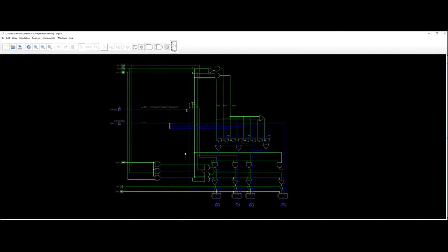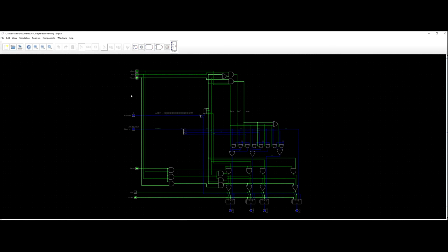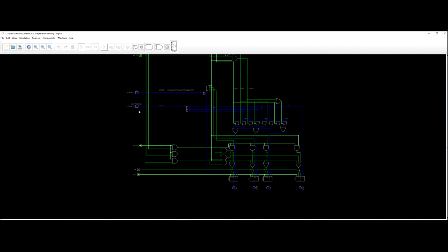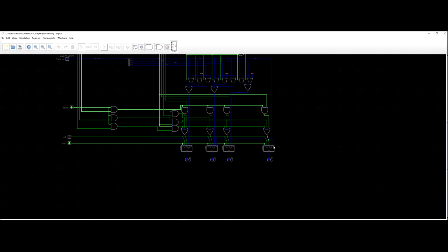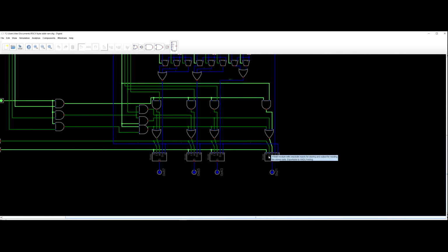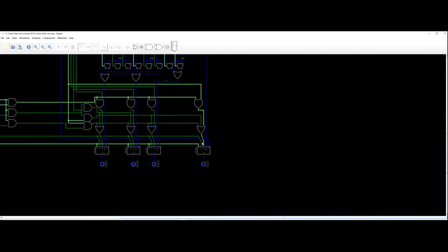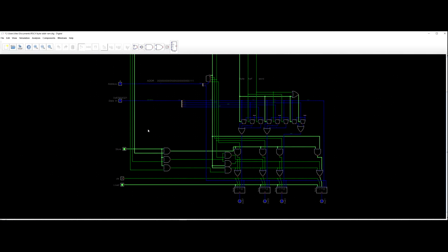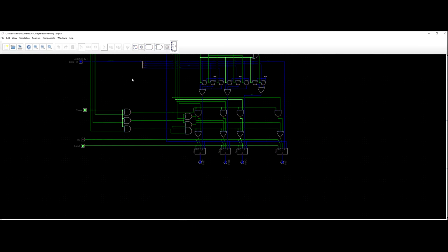Okay, so there is the control logic so far for storing. I just want to test it out a little bit more. If I say store byte at address 4, this is 0, 1, 2, 3, so a 1 should be here. So it should select this one at address 1. Oh yeah, I am at byte. Yeah, that's what it's doing. It's telling it to store here, and it'll store 21 there. If I go, say, to address 5, I can now overwrite 21 there by saying clock.